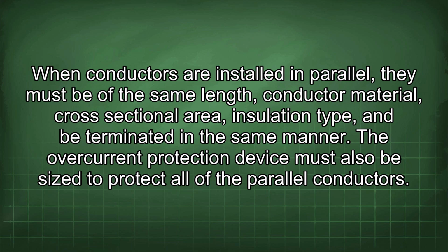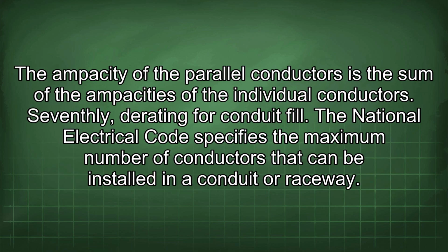The overcurrent protection device must also be sized to protect all of the parallel conductors. The ampacity of the parallel conductors is the sum of the ampacities of the individual conductors. Seventhly, the rating for conduit fill.